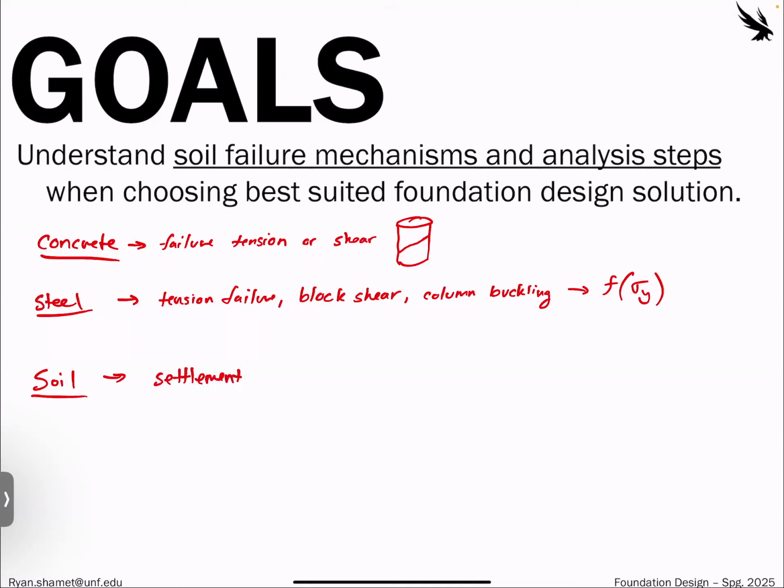And that's kind of tricky, because settlement is just the decrease in volume. So your building could be completely fine, but if your building settles 3 feet, what happens to everything connecting to that building? And what happens to the runoff and drainage and everything? That can be considered a localized failure or even a global failure. Though if your whole building settles evenly, that could be fine.